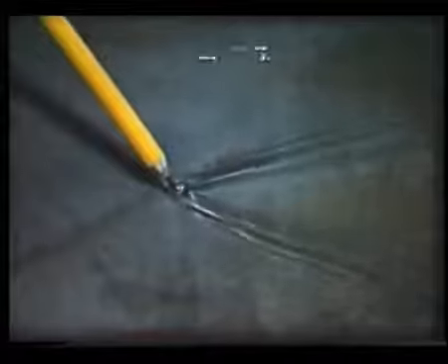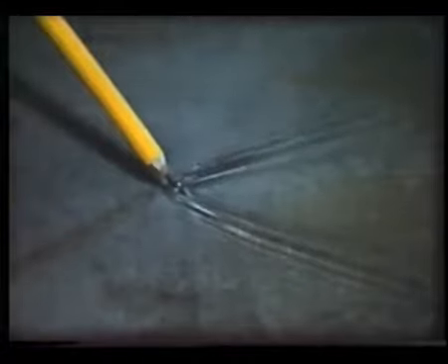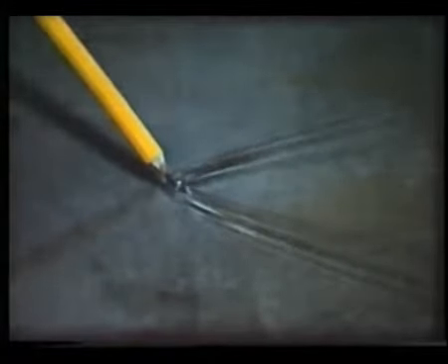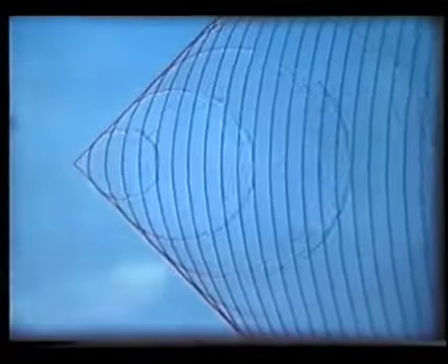A similar effect can be seen by dipping the point of a pencil in a fast-moving stream of water. Only the region inside the wave is influenced by the pencil point. The water outside this region flows on as though no disturbance existed. In the same way, the supersonic point can only affect the air lying inside the Mach lines, shown here in white. Ahead of the Mach lines, the air is undisturbed. Since all the disturbances coming from the point are infinitely small, the speed and direction of the airflow, shown here by white streamlines, don't change as the air passes through the Mach lines.